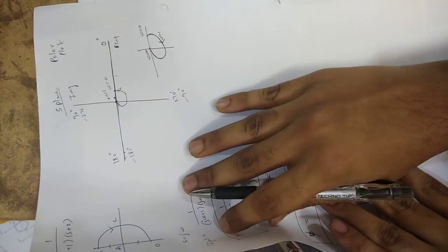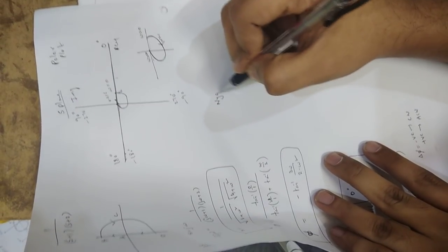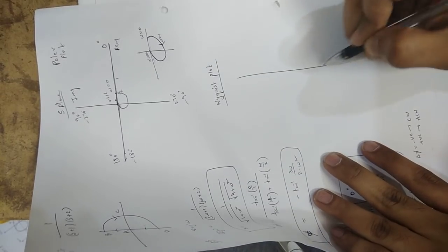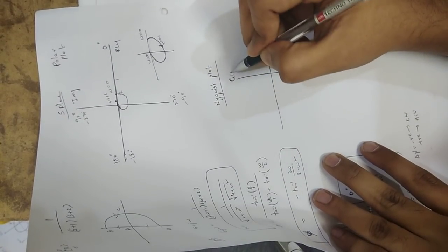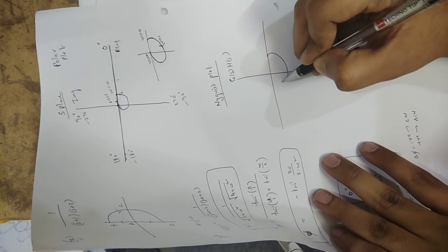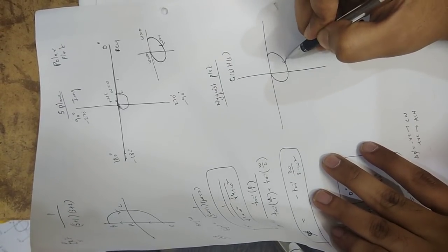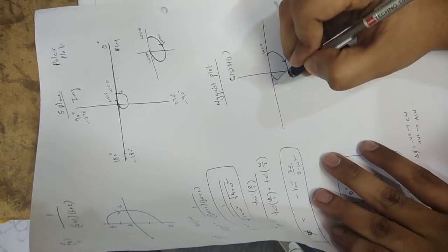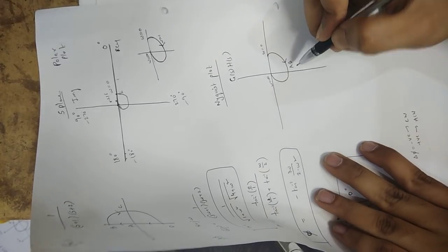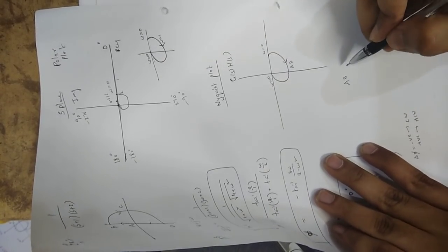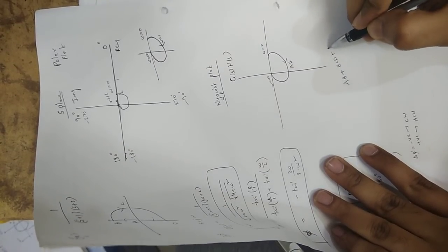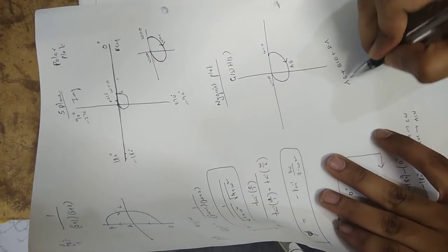Now for the same question, draw the Nyquist plot. Same, but the plane will be the G(s)H(s) plane. And the same thing we will be drawing here, the same clockwise direction, here omega 0, here omega infinity. This is the AB part, right? Now, what is the Nyquist plot? Summation of AB, BCD, DA. So we have done the AB part.